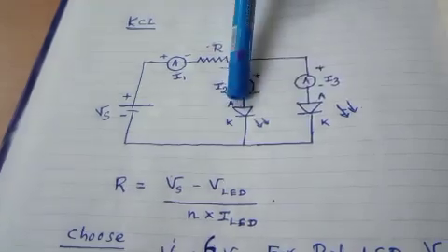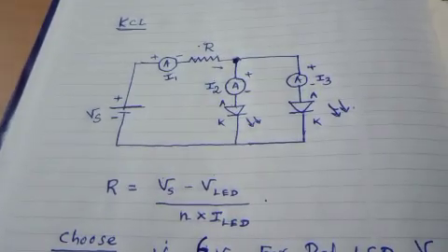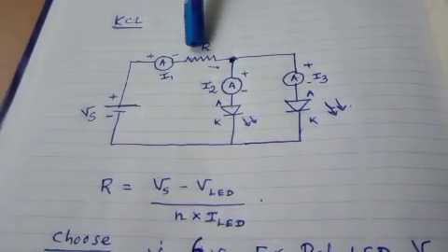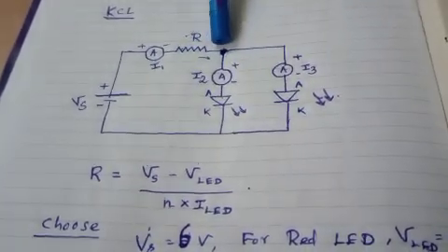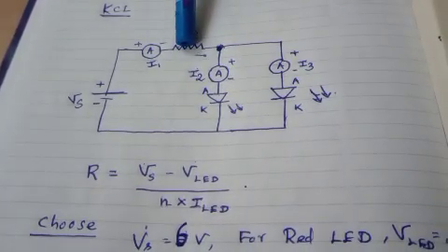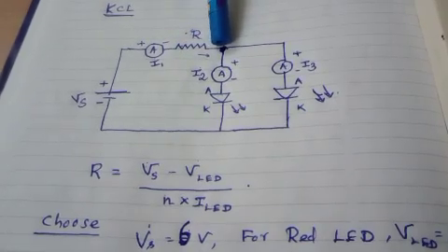Okay, so actually we are trying to make this circuit in this board. So now what I did is I connected these two LEDs in this breadboard. Now I am going to connect the resistor. These two LEDs are actually connected with one common point, right? So you see now this resistor is connected in series with this common point.